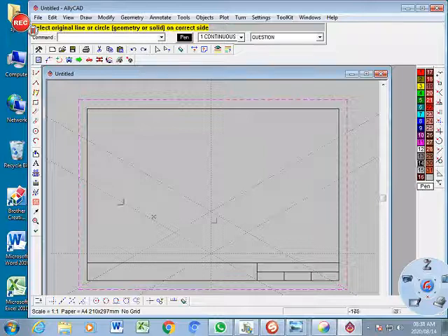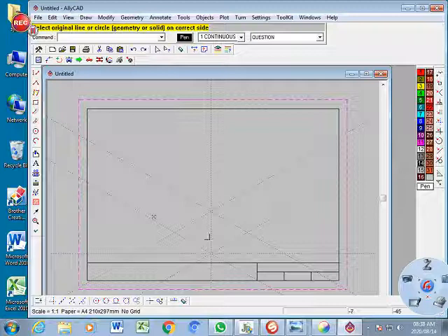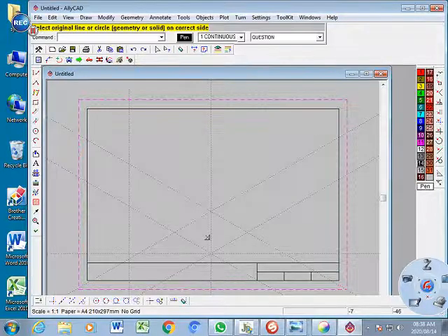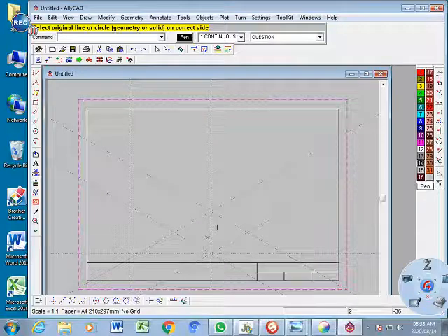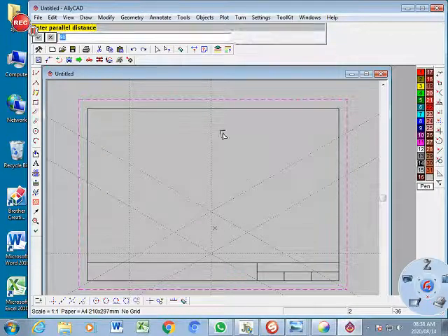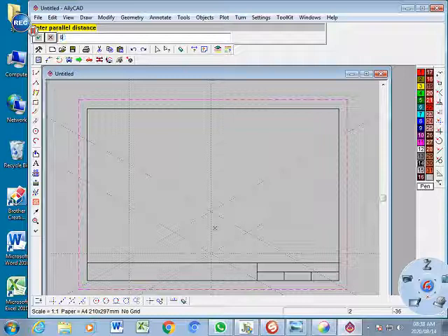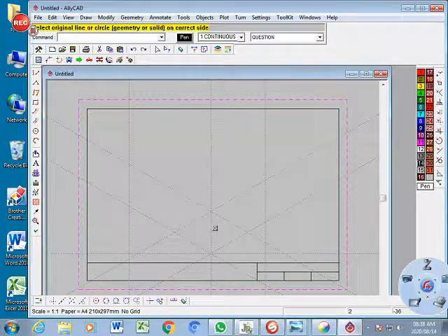So now you're going to mark off the length. The length this side of my A is going to be 60 plus 30, which is 90. So I'm going to click to this line on this side there. It's going to ask, the 40 will be there, but I'm going to change it to 90. And I'm going to click yes, and there it cuts off my 90, and I'm going to go to my width and I click on this side of this line here. It's going to ask me, the 90 will still be there, but I need the width, which is 20 plus 20 plus 20. It is 60. Type in 60 and I say yes, and there's my one side of my box.